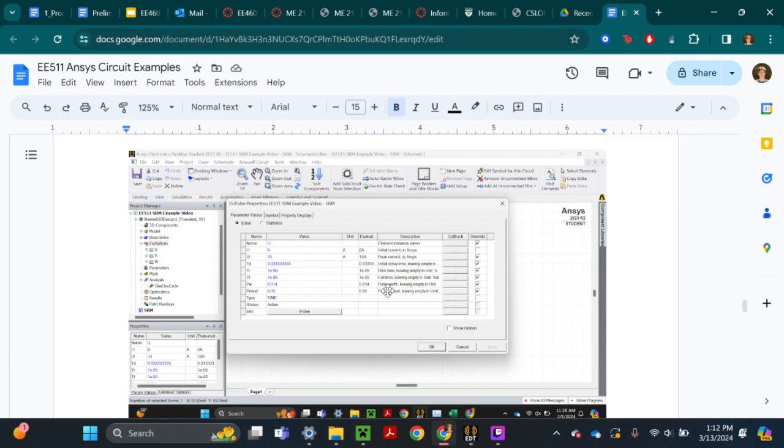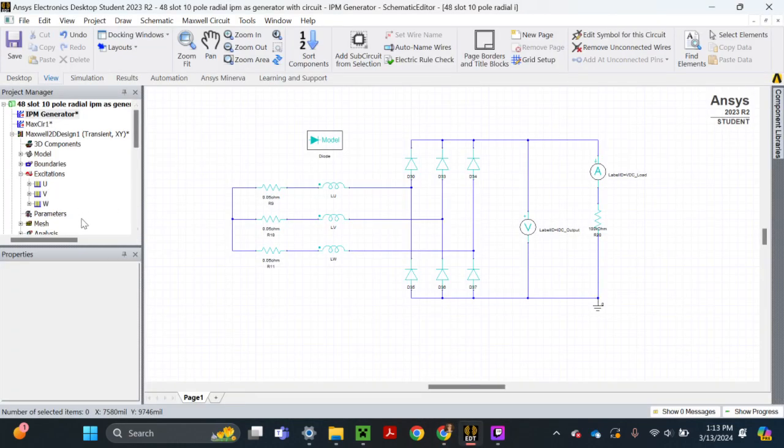It's just basically defining a step function, and you'll be defining what time it goes high and how long it stays high for, and then what time it goes low. And then you can define the frequency of that, or you define the period of it. So like every second it'll go high at 0.3 seconds and go low at 0.6 seconds or something like that. But because you'll be running it synchronously, depending on what speed your motor is rotating at, you'll have to decide when it'll switch, and based on the initial position of the rotor, you'll have to decide when it'll switch.